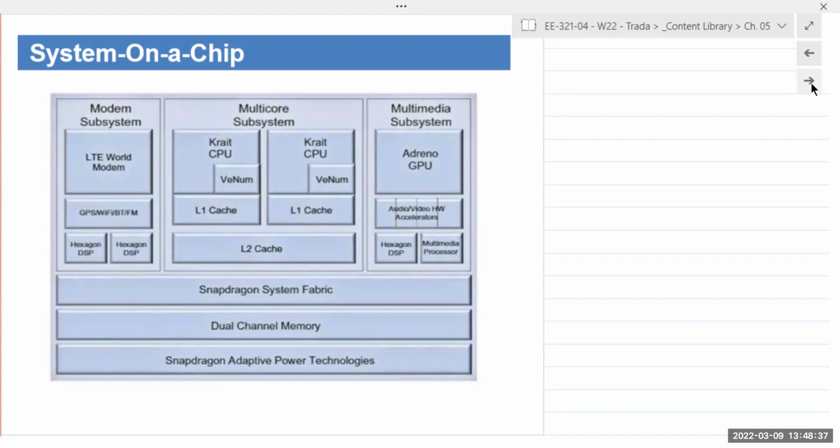The reason for that was all the chips were separate. Your processor was separate, your memory was separate, all of them were individual chips. More importantly, your modem, the baseband chip, was separate. Slowly but surely, they started integrating everything into one package. The simplest explanation of a system on a chip is that you took all of the different chips and put them on one piece of silicon. That is what SoC stands for. Modern day SoCs started incorporating everything in one.